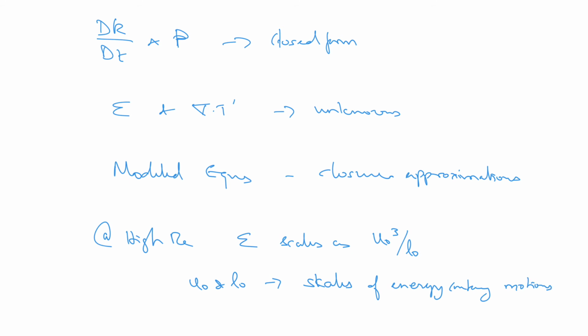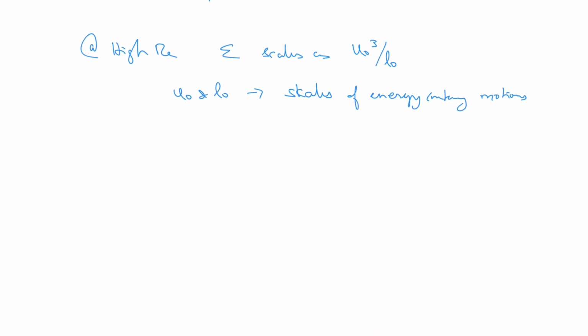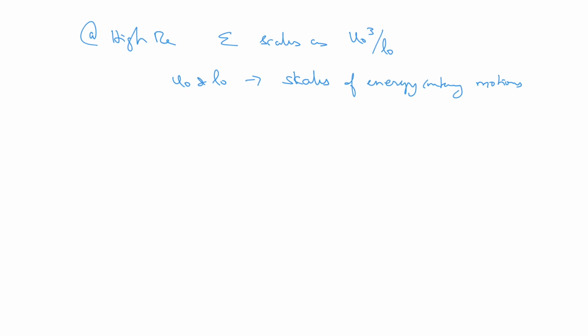So it is especially saying the turbulence scales or the energy containing motions, which is giving energy to the fluctuations. Now this epsilon is modeled as epsilon equals c suffix d k power 3 by 2 by L suffix m, where the c suffix d is a model constant.